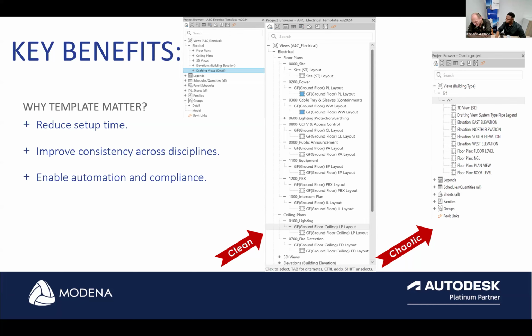Hi, Erica. Pre-project setup and client consultation: does client and consultant information sharing affect template development? Very, very good question. Again, you're leveraging project-specific requirements into a template. It is going to impact on project startup, bottom line. Okay, the objective is to minimize it, and that's where industry standardization comes in. So things like a BIM execution plan, you know, with mandated requirements, that's going to help.